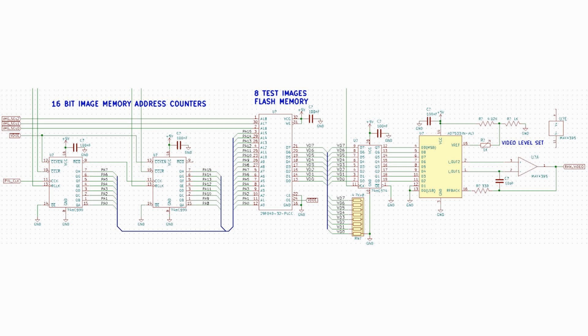This pixel clock originates in the sync state machine, and it's just canned pulses in one of the bit positions, and they come in bursts of 256 at a time, and then during the blanking period of time there are no clock pulses. These counters and the 19-bit counter are reset by the master reset pulse of the state machine. So once every frame, everybody gets reset back to 0, 0, or the upper left corner of the frame diagram I showed you a little while ago.